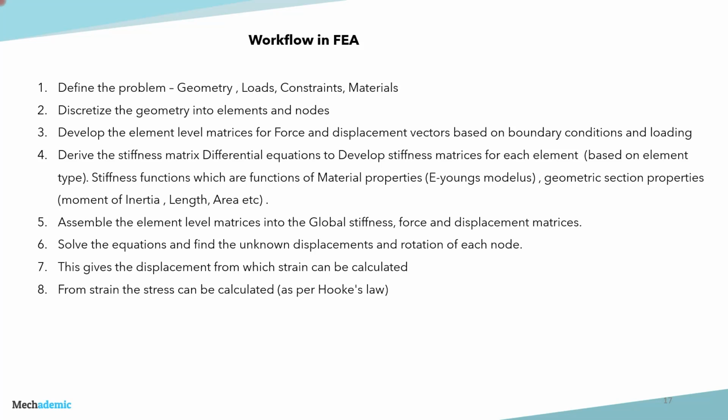Now when the matrices for the element level, the force matrix, the stiffness matrix and the displacement matrix are developed, these matrices have to be assembled to get the global stiffness, force and displacement matrices. And once the global matrices are assembled together, the solving will happen afterwards, and the matrices are solved and the unknown displacements and rotations of each node are found out.